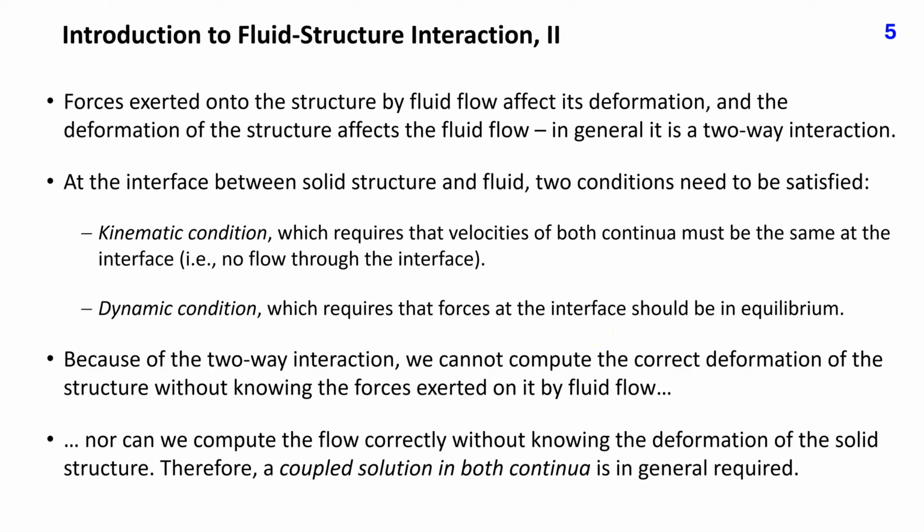Because of the two-way interaction, we cannot compute the correct deformation of the structure without knowing the forces exerted on it by fluid flow. Likewise, we cannot compute the fluid flow correctly without knowing the shape and position of the solid structure. Therefore, a coupled solution in both continua is in general required.